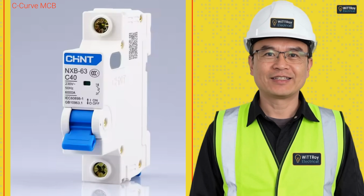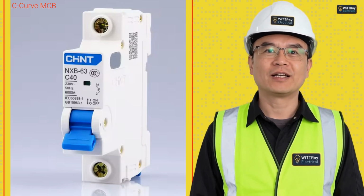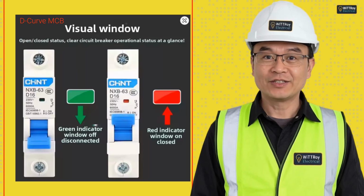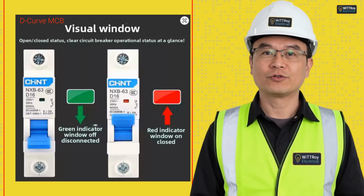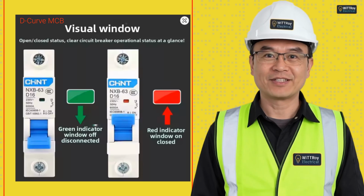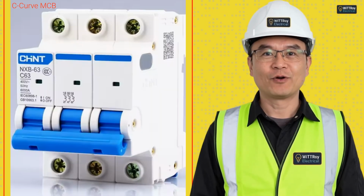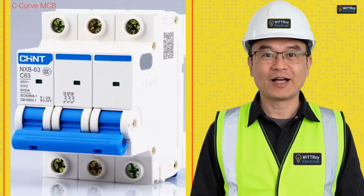Let's look at this device. It is a 1-pole 230 volt C-curve 40 amp MCB. Let's look at this device. It is a 1-pole 230 volt D-curve 16 amp MCB. Let's look at this device. It is a 3-pole 400 volt C-curve 63 amp MCB.